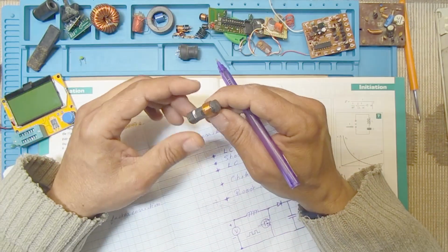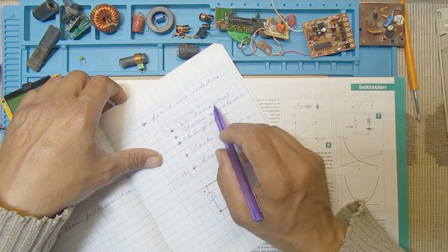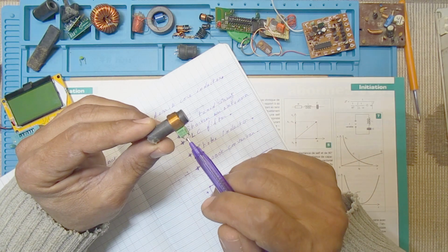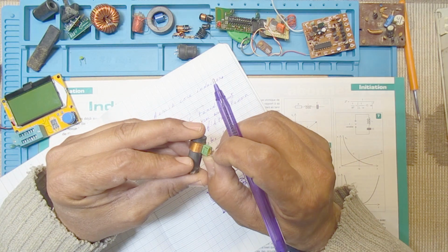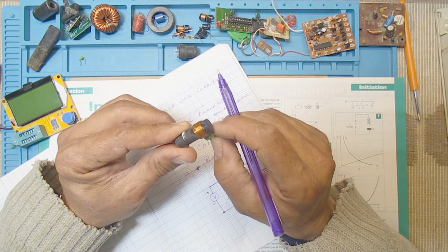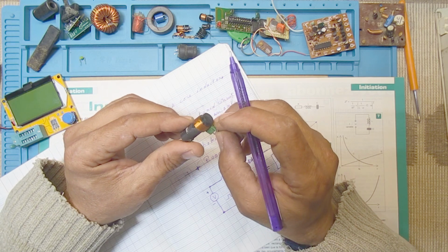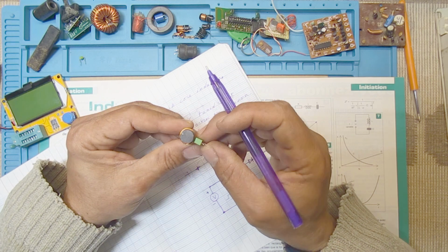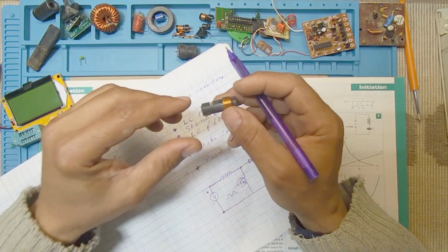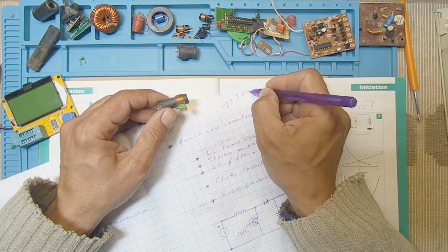And for the ferrite core, we have many uses of the inductor. The first one is the LC tuned circuit. For example, this circuit is formed by an inductor and a capacitor here. It's used for receiving the signal from the transmitter. We have a transmitter that transmits the time over the long wave. This is tuned to 77.5 kilohertz.